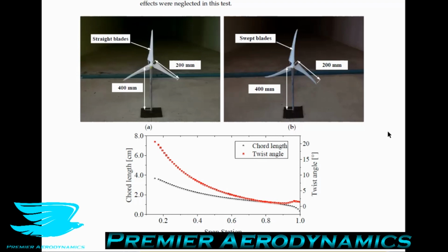And the reason why we have two different sections here is that often we have different sections in a wind tunnel to have different flow conditions. So for example, you might want an atmospheric boundary layer wind tunnel, and another one where you want an aerodynamic wind tunnel. Or in this particular case, they have different cross sections. And the reason why you might want that is to be able to accommodate bigger objects and not have to worry about the blockage ratios. And I've done podcasts on the blockage ratios before and how oftentimes the blockage ratio is too large even for correction factors to make them useful, really.